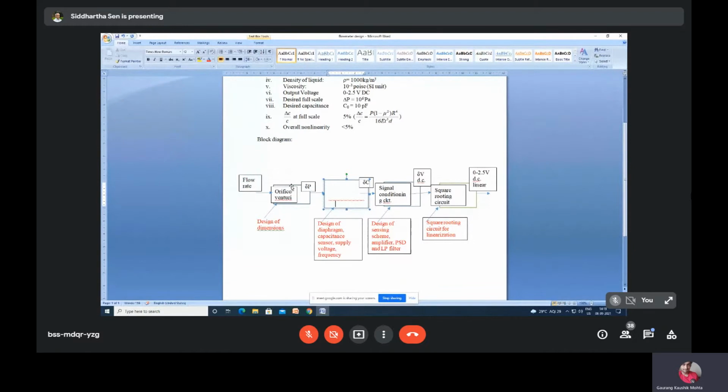If it is an orifice, what should be the shape of the orifice plate, what is the angle, and if it is a venturi, what should be the converging angle and the diverging angle. These things are partly available in standards and many other places. Whenever I design the orifice, I will also look into the dimensions, and from that I will have to calculate